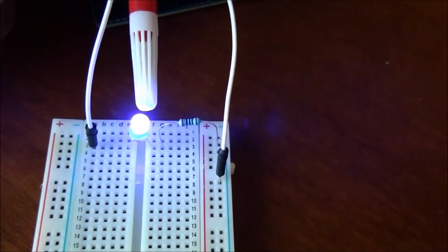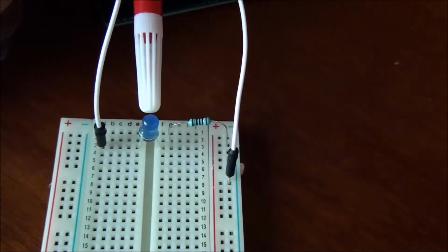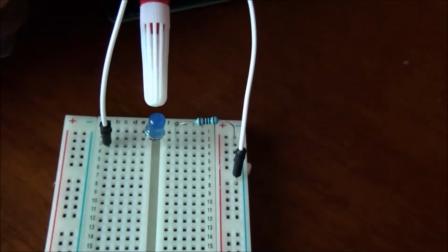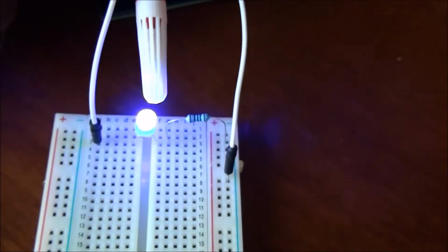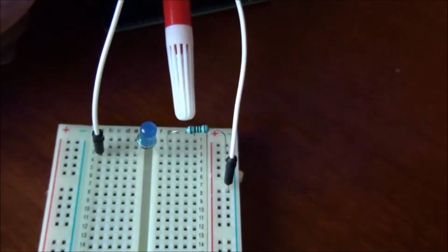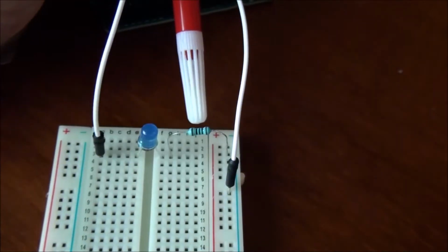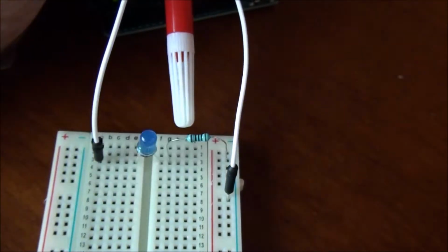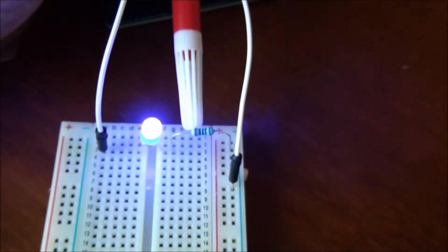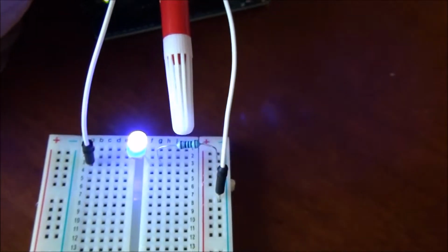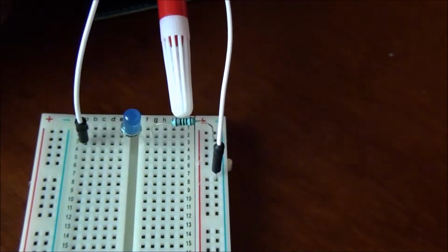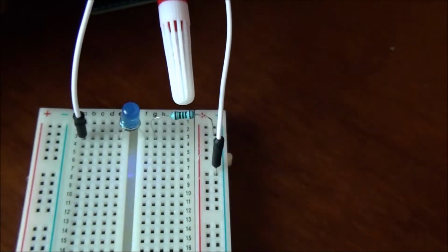If too much current goes through here, you'll burn it out in no time, even within a few seconds. It may actually flash, and then it'll be dead. A dead LED is useless, so you have to chuck it away. If it's about 70 ohms or 80 ohms, 90 ohms, it's no big deal. But if you're building a permanent project, not just prototyping, you want to get the right resistance. If you're just testing, 70, 80, 90, don't worry about it. But for long-term installations, get the right resistance.